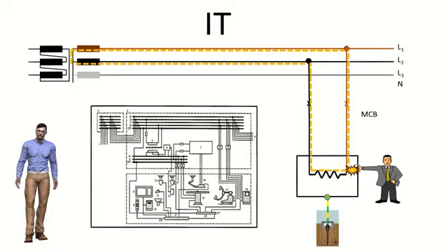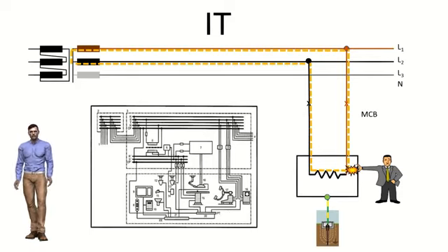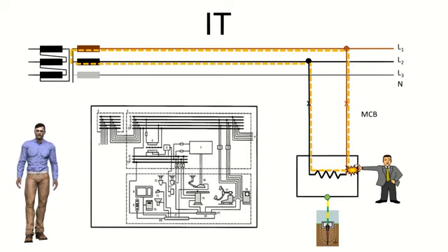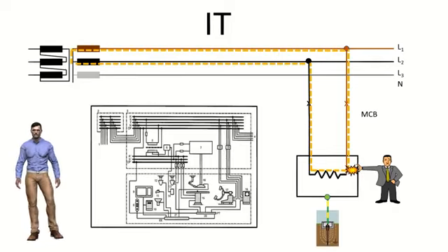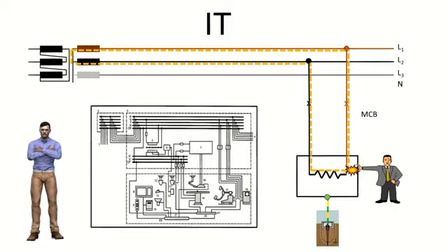In this type of installation, an installation monitoring device constantly monitors the installation, causing an audible or visual alarm in the event of a first installation failure, but allowing the continuity of the installation, being mandatory to locate and eliminate the first installation failure. In this way, life support teams in an operating room can continue to work during a patient intervention, even with a first failure.